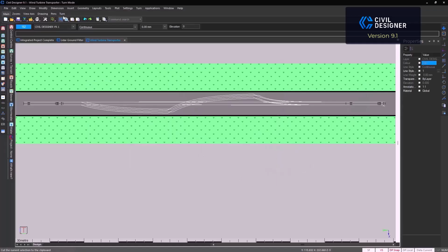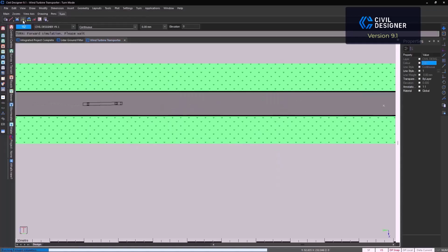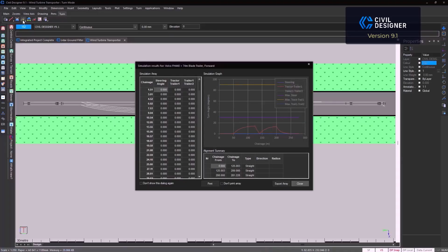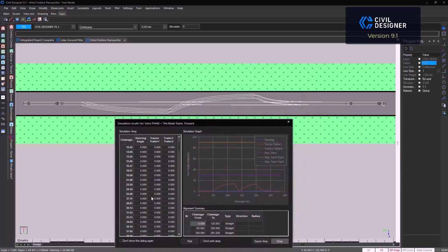During a dynamic simulation, the trailer angle can be changed on the fly by pressing the control key and rotating the mouse wheel simultaneously at any stage. The steer linkage graph shows the difference between the tractor and the trailer angles.